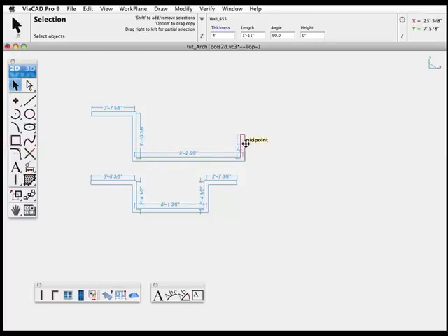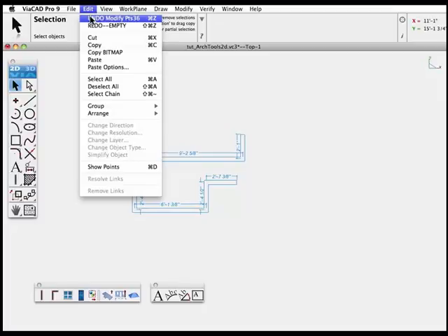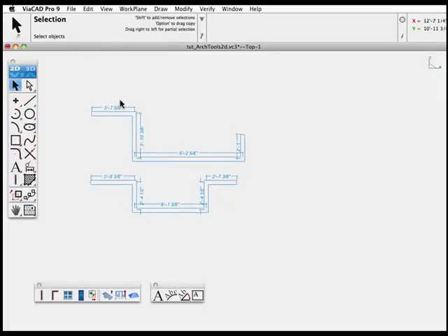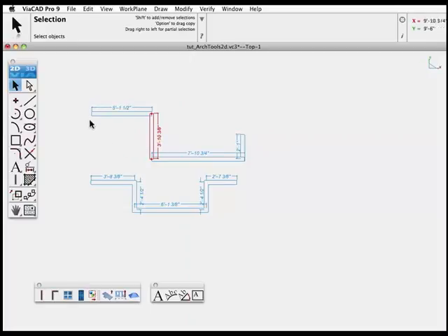To move a wall and maintain its relationship with other walls, drag around the endpoints of the wall and its adjacent walls. Move it to a new location, and it keeps the endpoints connected. To move a wall endpoint, simply drag around that single corner and drag that point with your mouse. Now let's delete these walls and talk about the options for walls, the wall styles.